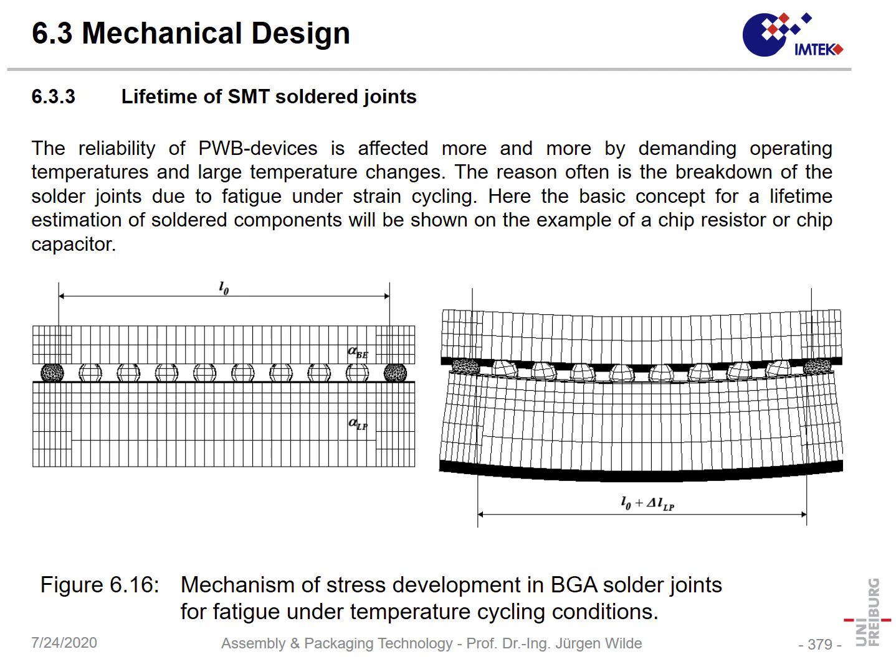That deformation, for one, means we have some bending, we have some linear change of geometry of our BGA on the printed wiring board. But on the other hand, when you look at the solder balls, you can find that you have a strong shear in the solder balls, and here you can also see that evidently the shear strain is again larger the more to the outside of that assembly you are.